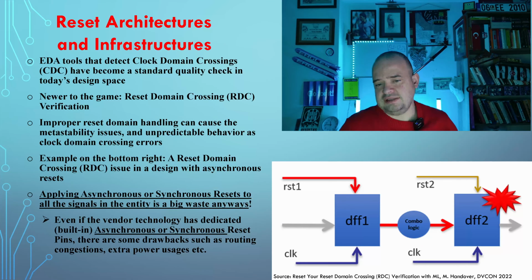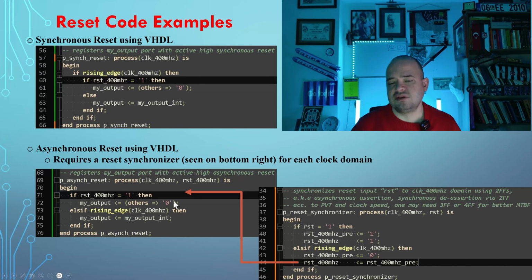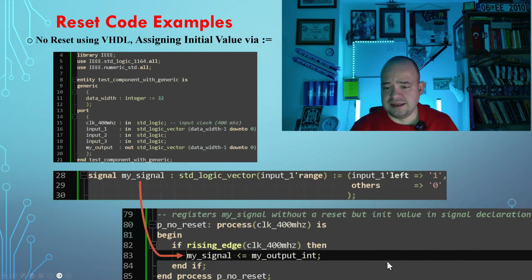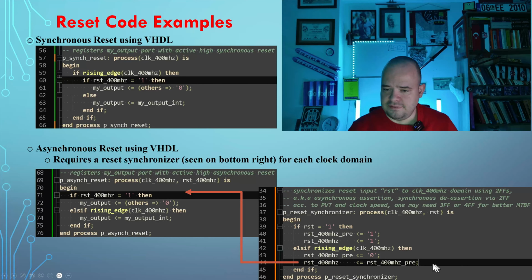meet that setup recovery time, especially when the fan out of this signal is really high. Let's say it is more than 1,000, or sometimes it happens actually if you use it extensively, it becomes 5K or more. Then you are getting negative recovery slacks most of the time, and then you need to clone this reset synchronizer. So you need to do two different reset synchronizations.